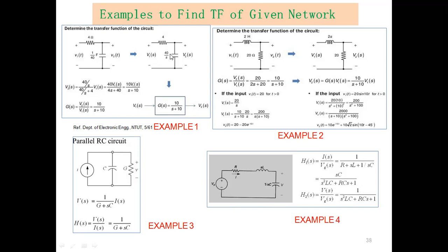Now what we are supposed to do here is use the transfer function. We are supposed to calculate the value of V2(s). How can we calculate it? We have the total voltage V1(s). Actually, they have not given the value, but we can take the voltage V2(s) in the form of V1(s) by using the voltage divider rule. So if we use the voltage divider rule, what will be the rule? V2(s) is equal to the value of the impedance here. So what is the impedance here, 40 by s?